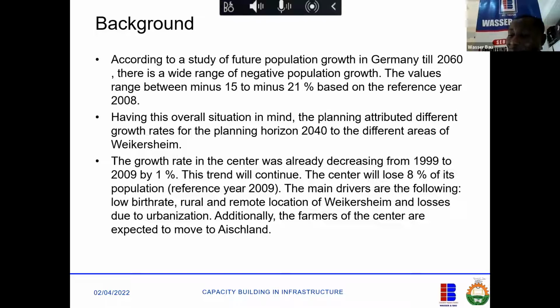If you are piping to an industrial area, as soon as you get to the industrial area, your pipe size must increase, even though you can use a plug and lock it. So that in the future, when development gets to that point, they just come and open your plug from the manhole, put in a new pipe, and the system continues. This is where experience comes in.